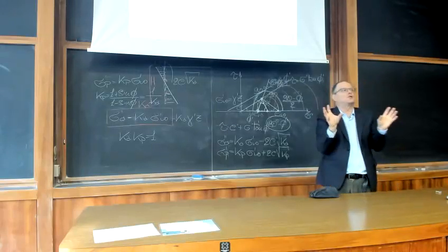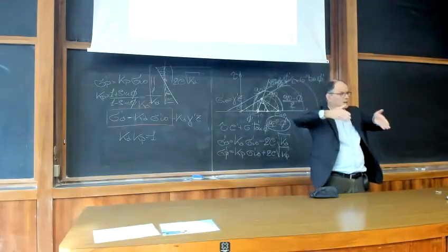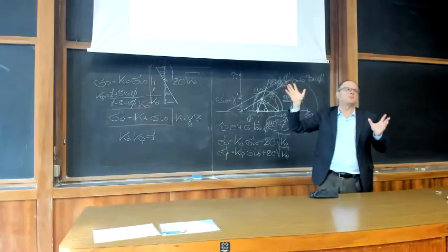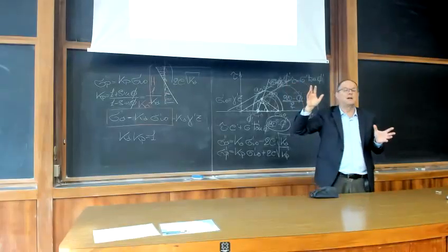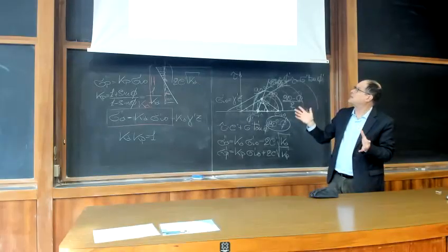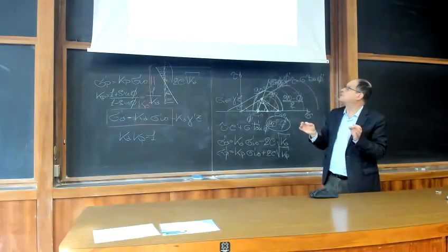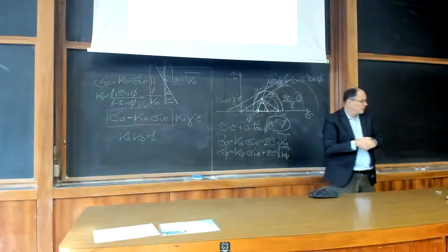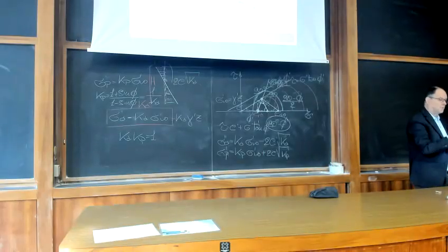But essentially these are the two mechanisms that you have for a deep foundation, whereas for a shallow foundation what happens along the sides is typically neglected, is not relevant. So that's the main difference between a shallow and a deep foundation. If you have something in between, you might have that both mechanisms are important and you have to consider both, but essentially a shallow foundation, irrespective of this geometrical ratio, is when you have only the bottom way of interacting with the structure.